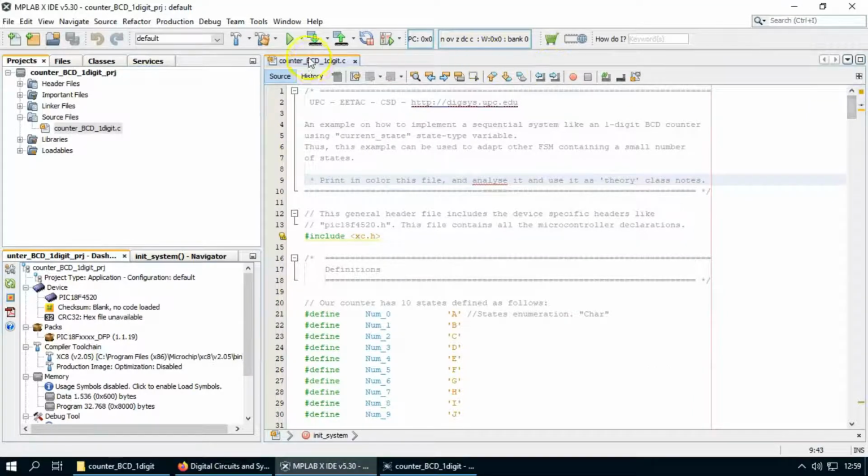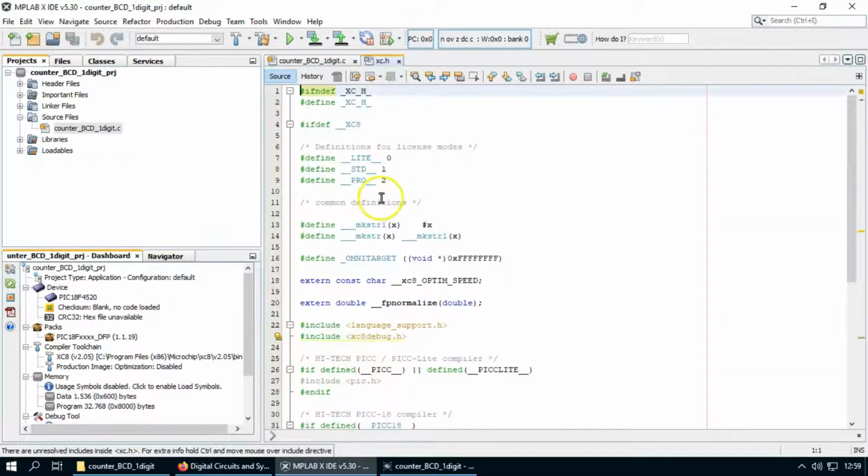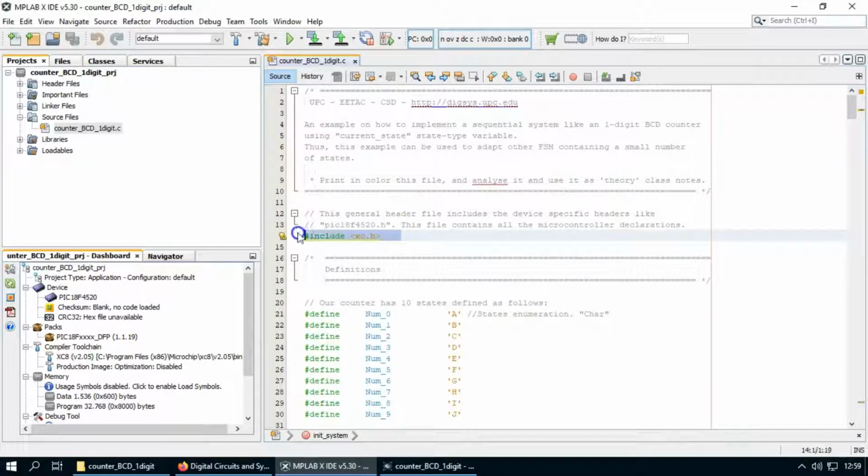So once the code is written, let me pay attention to the include. You know, the include exe, this header file contains all the other files. So you can go to the tree, you see, you can go to the last definition. You have here a single file project for convenience, but your file includes many other files with all the definitions associated to this microprocessor. And that's the great advantage of using this integrated development environment that keeps it all just that practical.